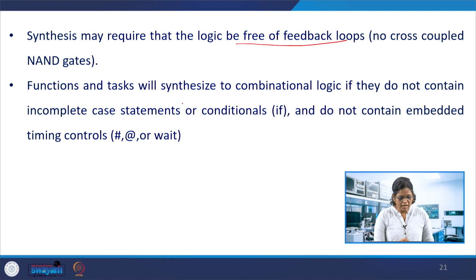The functions and tasks may be synthesized into combinational logic, but if there is a case statement or if statement that doesn't have the default case or all the options for the outputs, or similarly a conditional if statement that did not have an else statement, it won't synthesize into combinational logic actually.